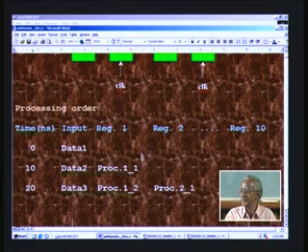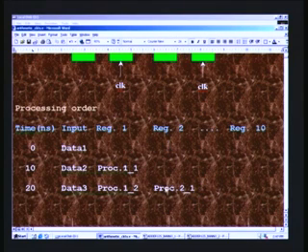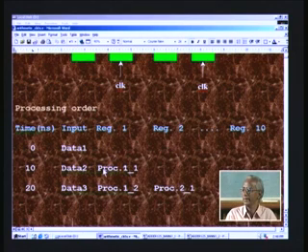In fact, it happens in between, but the actual process result is registered only with the arrival of the second clock, that is at 20 nanosecond, and when this happens, data 2 which was processed in process 1 will be registered in register 1 here, and that is the reason why 2 has been appended here. This one denotes data 1, data 2, data 3, whereas process 1 pertains to register 1, which stores the intermediate result of process 1. In this fashion, process 1, process 2 up to process 10 are all stored in register 1 through 10.